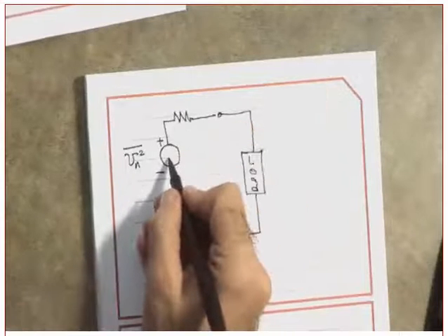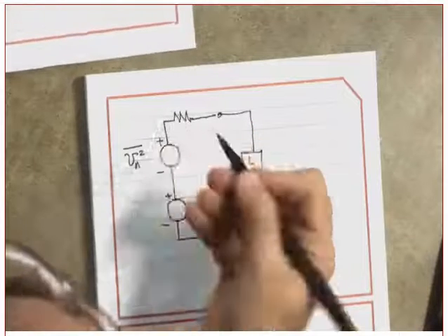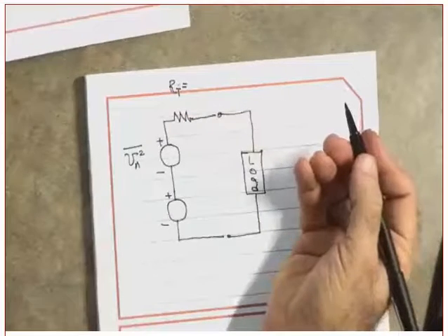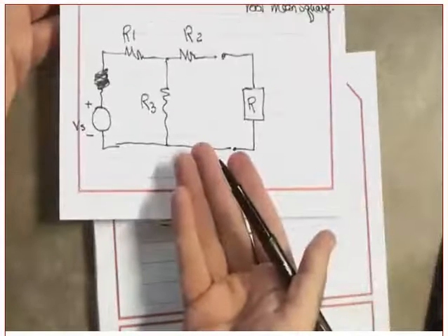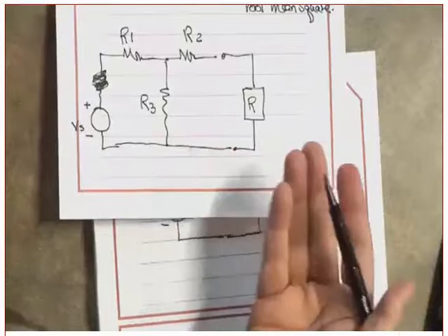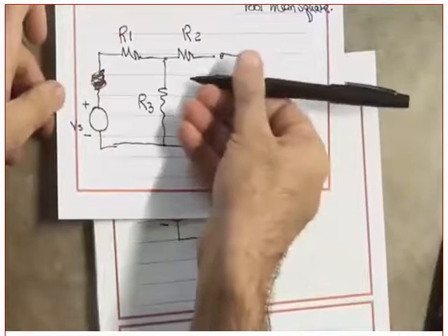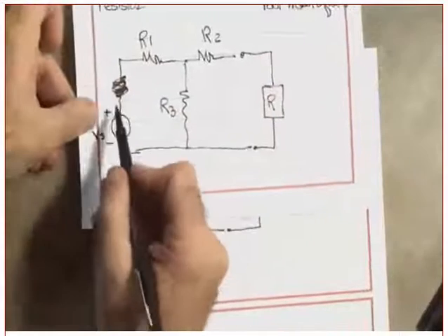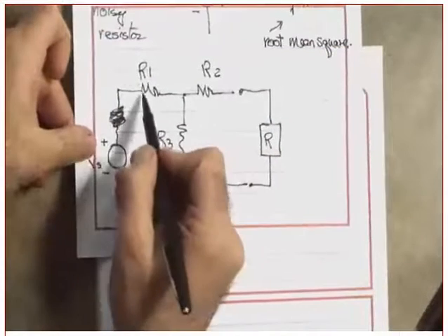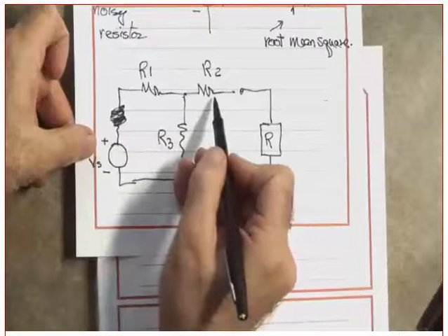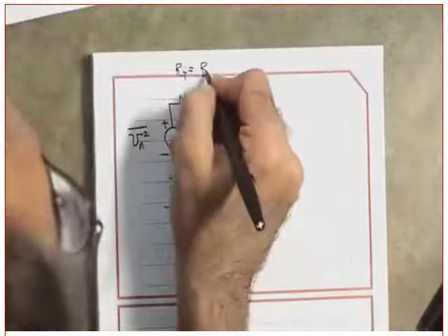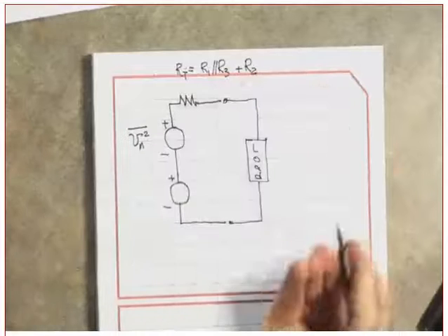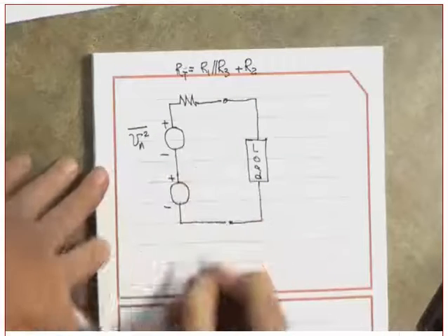Noiseless, because I incorporated the noise in here. But what is its value? How do you find the resistance here? Using Thevenin's. What do you do to the source? Short circuit. So what do you have? R1 in parallel with R3, in series with R2.